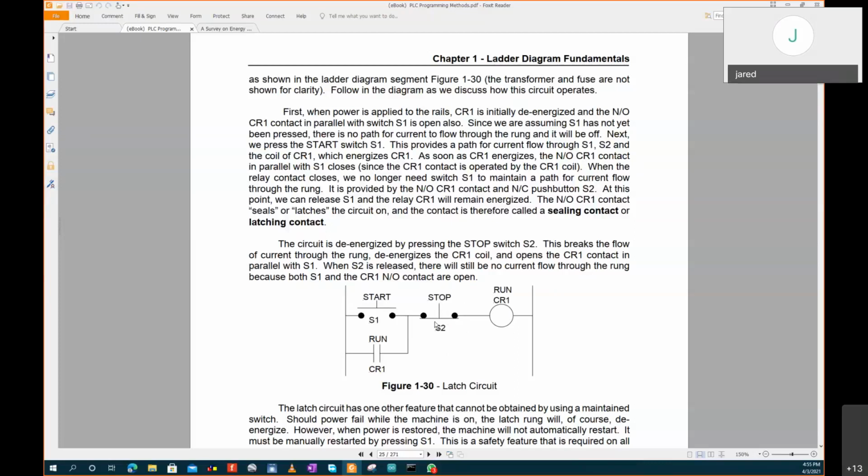So if you release power from this end, this is a latched circuit from here to here. Now that you pressed here, power flew to this side, then took this reference, it came here, it held the circuit. So this circuit is on continuously. If you want to break the circuit, you press this button here, and then power disappears. So when power goes off, this one loses power, and because this one is not pressed, this one will lose power and the circuit becomes off.